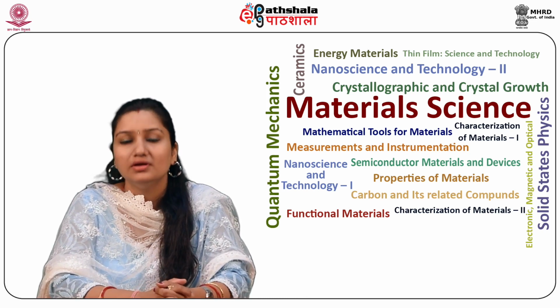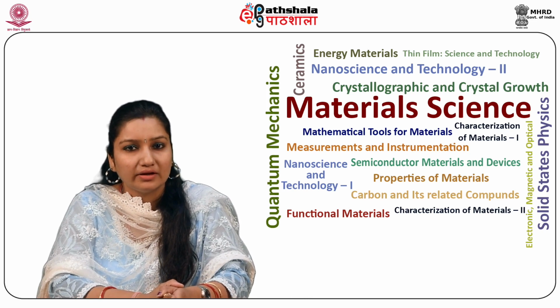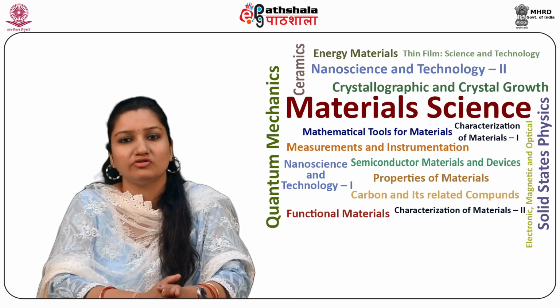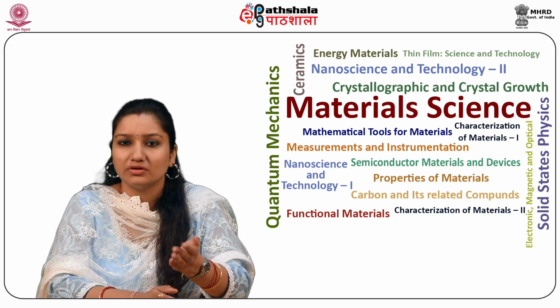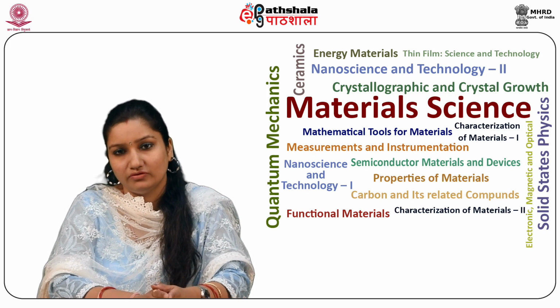For example, thermal evaporation is simple and cheap, but there is considerable amount of waste of source material during the process. While in electron beam evaporation, multilayer deposition is possible, but it is very difficult to control the deposition rate.